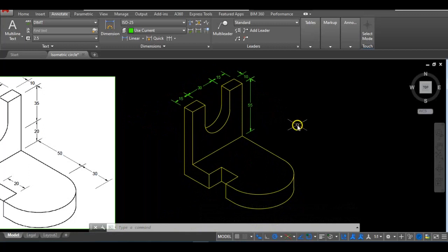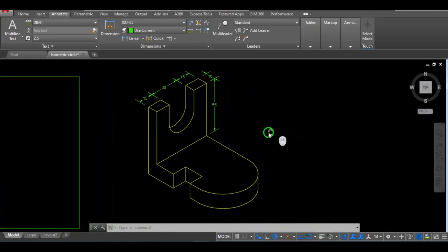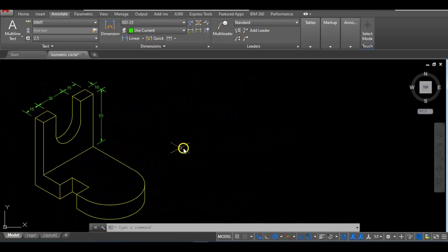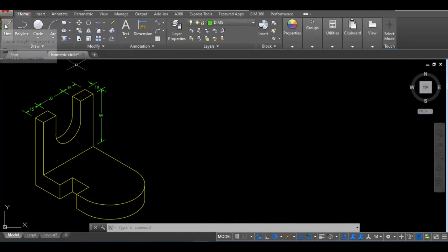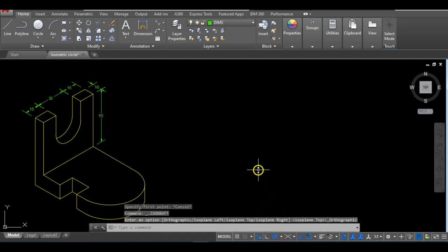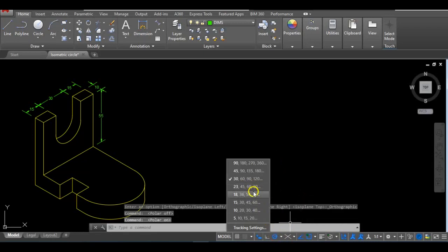And I'm going to be demonstrating that this doesn't only apply to isometric drawings. I'm going to be doing the same thing for an oblique drawing. So I'm going to be doing an oblique cube, and let me just say it may not look like a cube when I'm done because I drew in Cavalier oblique. Don't worry, we can look at oblique in another video. So I'm turning off the isometric snap mode, but you really don't have to. And I'm going to be changing my polar snap angle to 45 degrees.